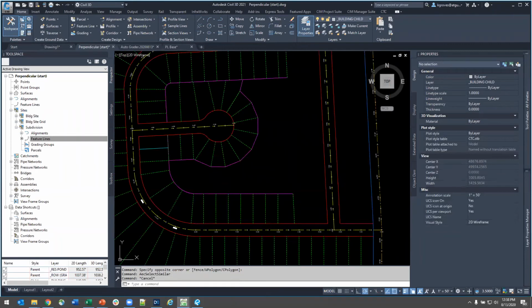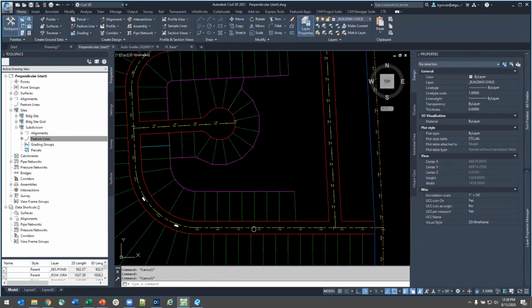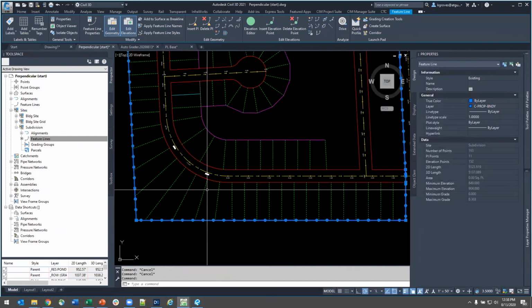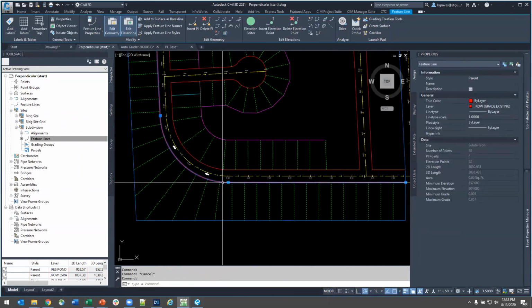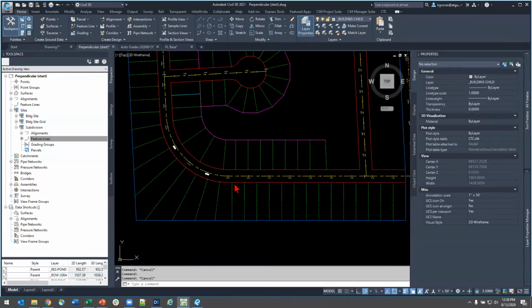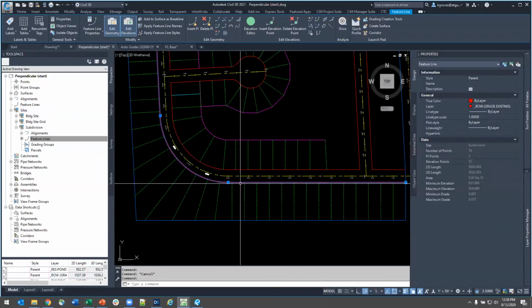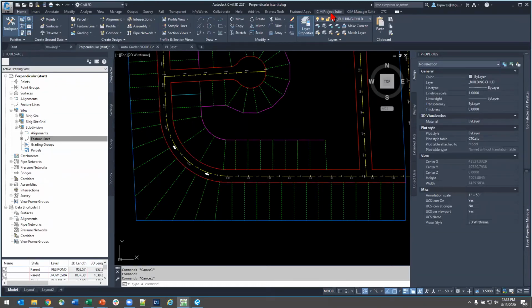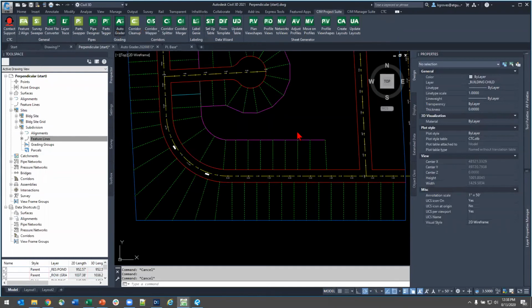So what I have is I have the highest style here on my back existing. That's always going to control the elevation. I have my parent style for my right of way. Now what I'm going to do is I'm going to modify my grading family to start from my right of way, go outward, and then it's just going to touch these other ones and take on that existing elevation. So here, go ahead and run AutoGrader.